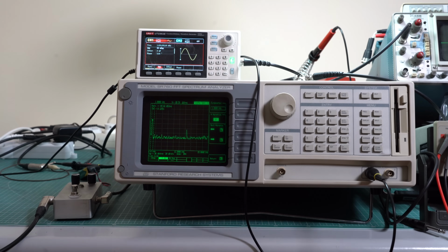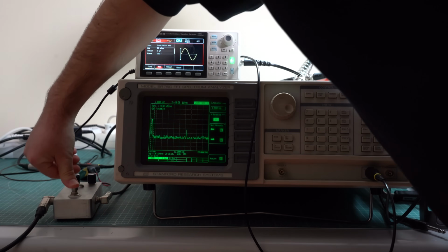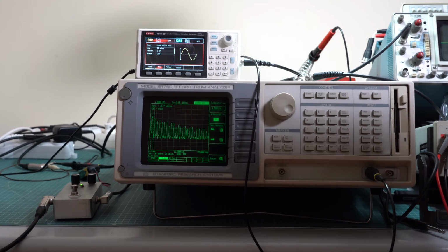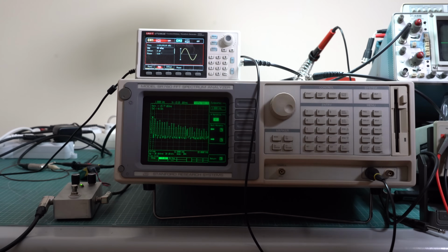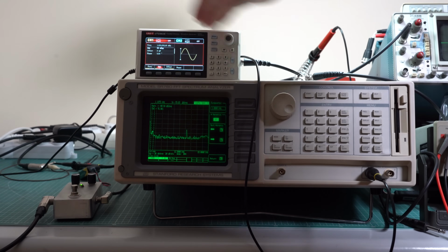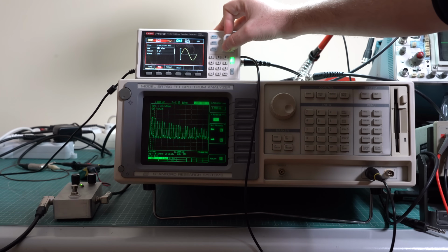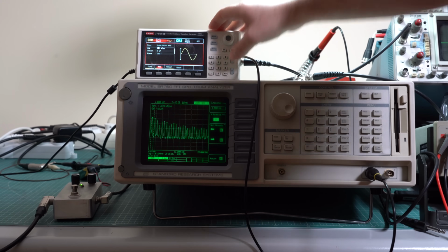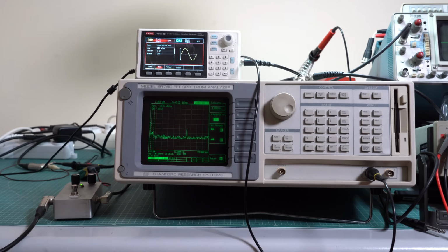So I think this is an acceptable amount of distortion. Let's enable the pedal and see what we get. So now, as you can see, the distortion is much higher, it's at around 50%. And by overdriving the pedal even more, we can get even more distortion if that's what we wanted. So let's increase the signal level. And as you can see, the more input we give it, the higher the distortion gets. So we got to a THD of around 80%.